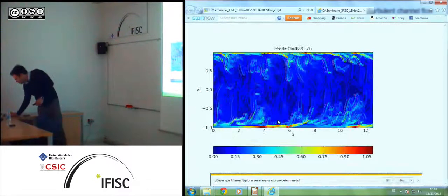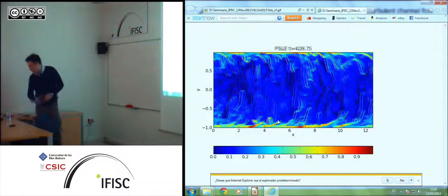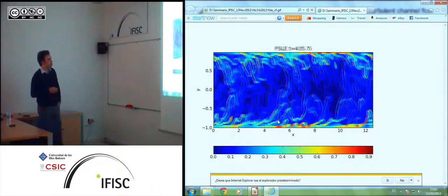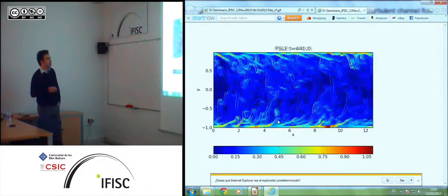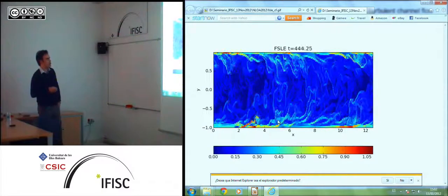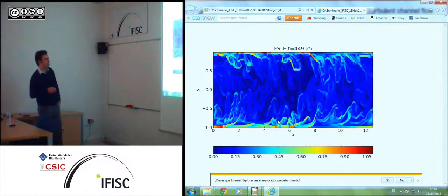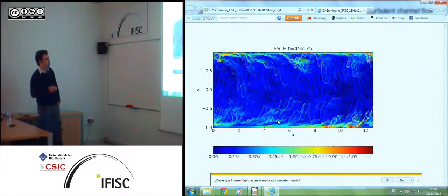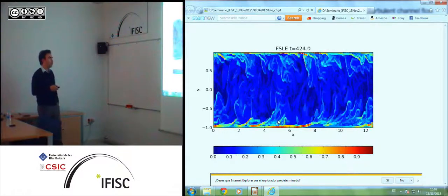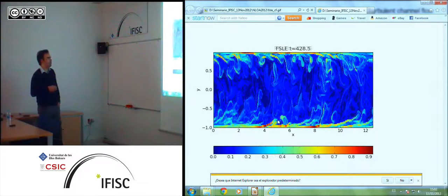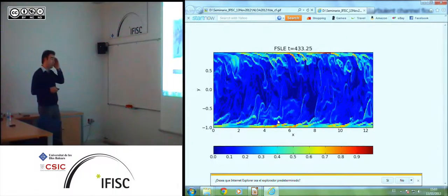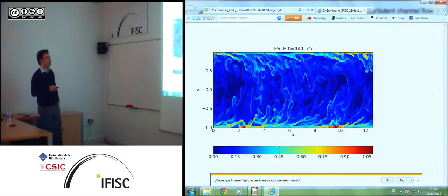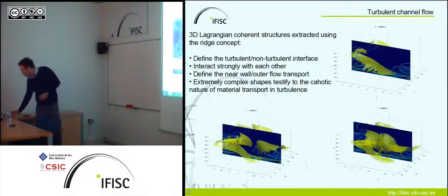So of course this field evolves with time, and you see all kinds of phenomena, but the most predominant are these hairpin vortices. Note that they also appear in packs. Here is one pack, then there's nothing, and then another pack will start. Actually, this is periodic, so probably it is the same 2 or 3 packs. But comparing to the Eulerian flow, we think the Lagrangian picture is pretty much correct in representing the same things, but in another way.